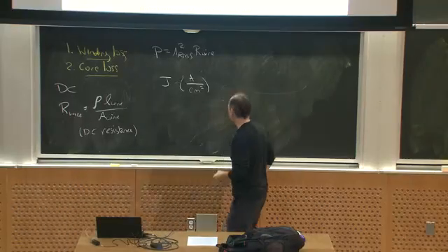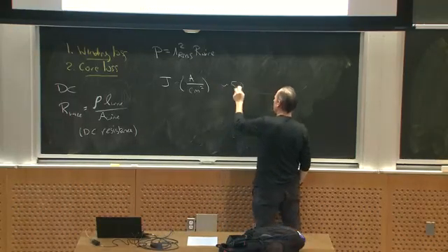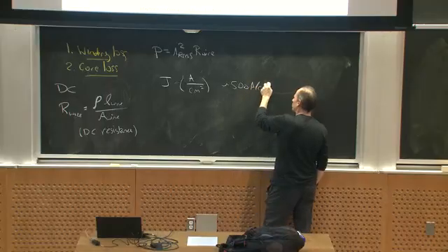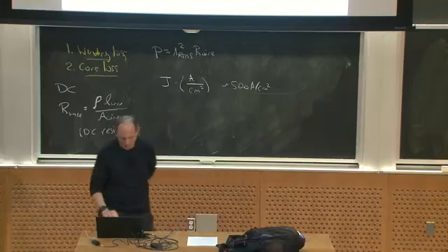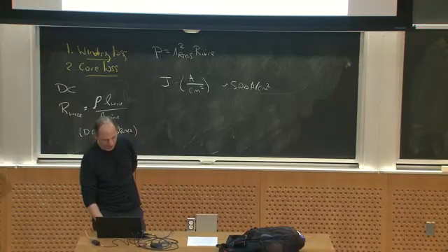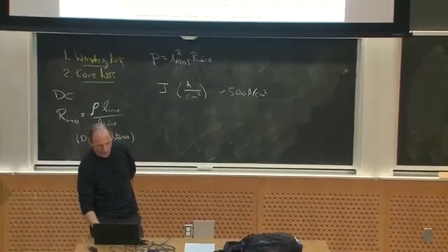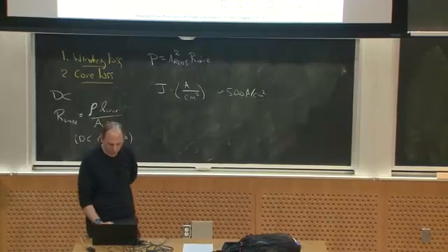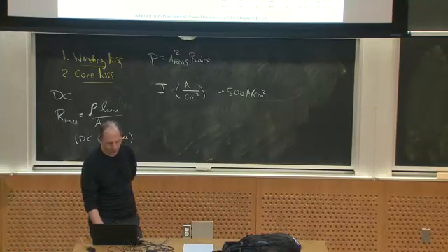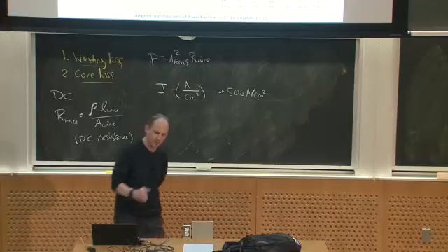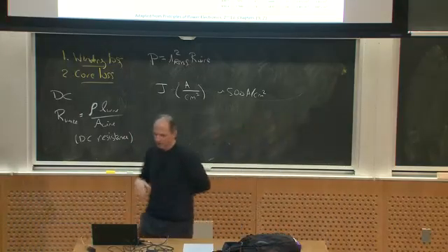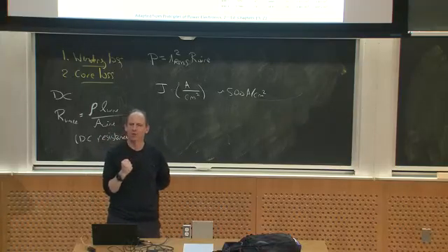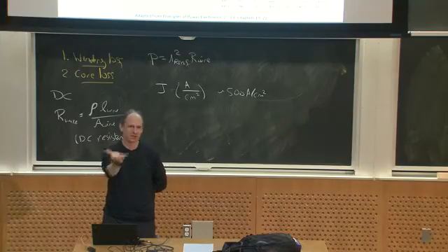A typical number might be on the order of 500 amps per centimeter squared. And we're talking about RMS values, okay? But again, it depends on scale. This chart, which I pulled out of KPVS, shows if I took this kind of core, which is known as an RM core, or rectangular modular core, the RM4 core is really small, the RM14 core is the biggest, maybe getting close to the size of my fist. And this shows if I have only winding loss, how hot will the thing get, based on measured data.